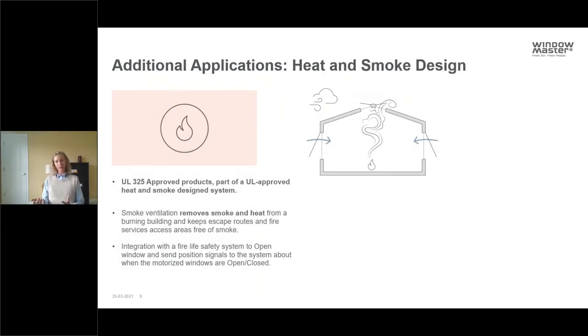So another great application for using window actuators, especially in the North American market, is to use it in a heat and smoke application. Here I'm talking about using an actuator and our control panel as part of a full fire life safety system. Our controllers and our actuators won't be based off of Windowmaster scheduler. It'll be connected to a Notifier system. But our parts, the actuator and the controller, would be parts of the full system to allow smoke and heat